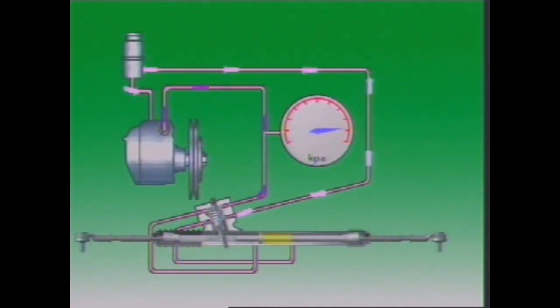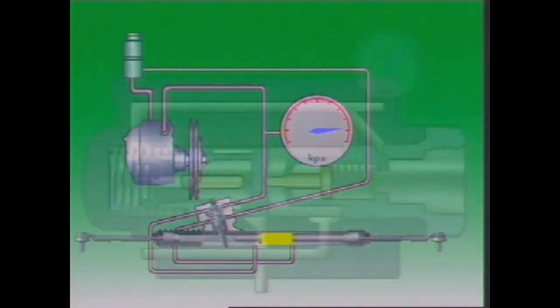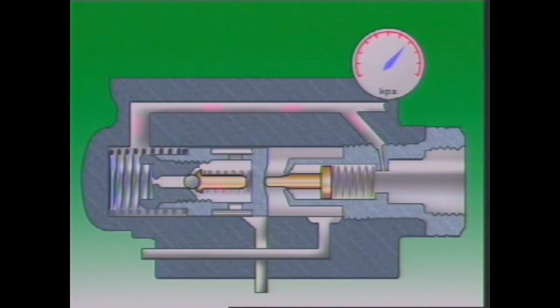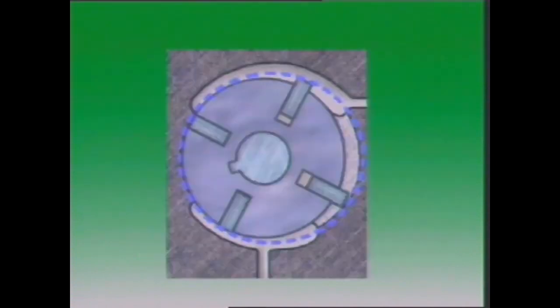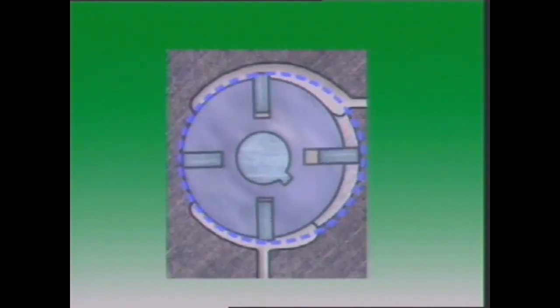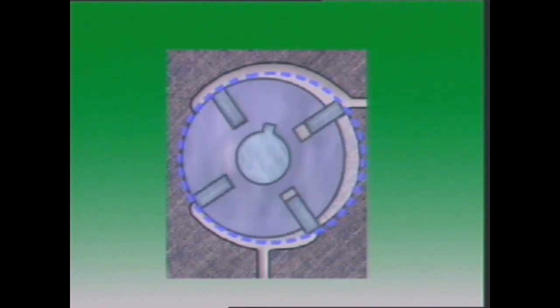With the steering wheel held at full lock, the steering rack power piston chamber becomes fully pressurized and fluid flow stops. This high pressure is transmitted back to the spring end of the control valve, opening the pressure relief valve. A small amount of fluid passes through the pressure relief orifice, providing a pressure drop. The valve moves and uncovers the return port to the pump inlet. A predetermined relief pressure is thus maintained. The pump is normally a vane type with sufficient capacity for all operating conditions.